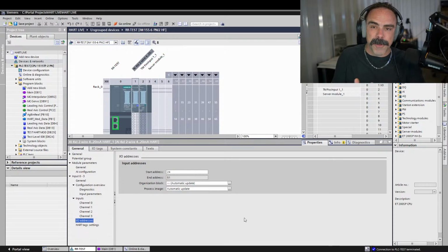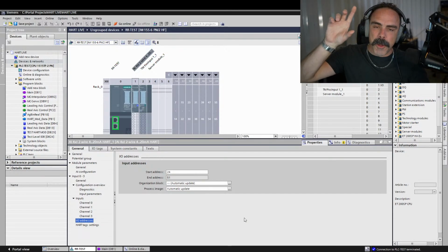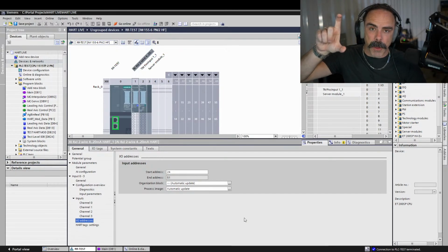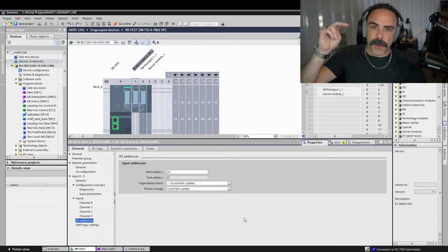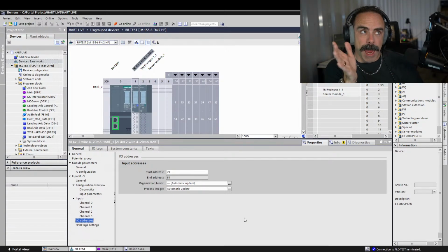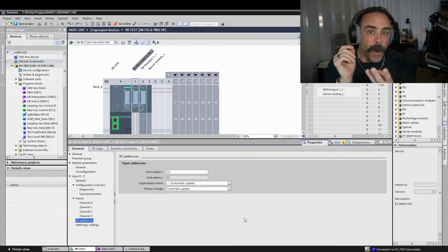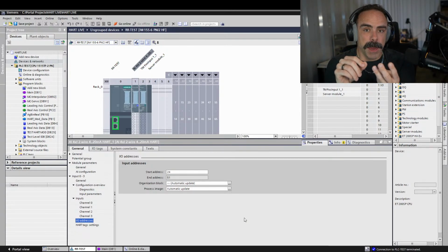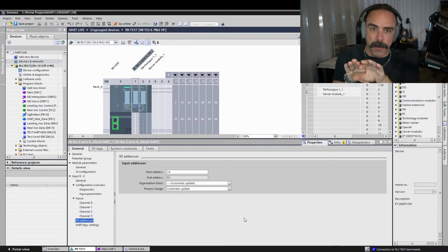A real value takes up 4 bytes, whereas a word takes up 2 bytes. So you have all of your analog inputs, which are words. So you have 24, 25 is channel 0, 26, 27 is channel 1, 28, 29 is channel 2, 30, 31 is channel 3. So those are your 4 just kind of percent value regular analog inputs.